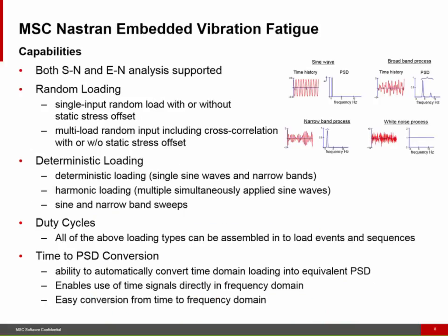So a few words about the capabilities for the embedded vibration fatigue. We have both stress life and strain life in this first release of the embedded vibration fatigue. We have random loading, which can be single input with or without static stress offset. And it can also be multiple input loading, where you can also add the cross correlation between the different inputs.